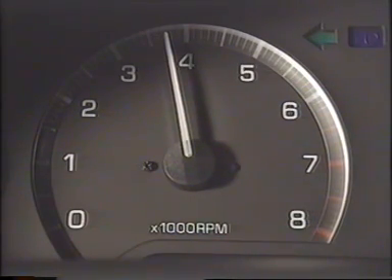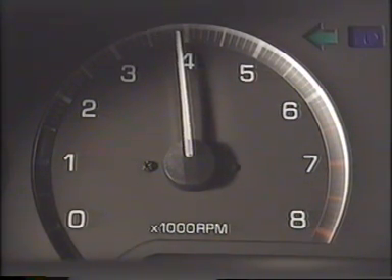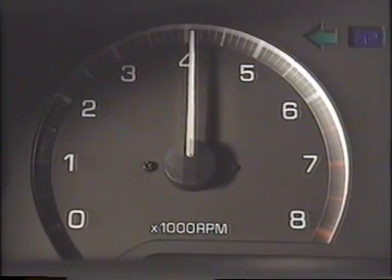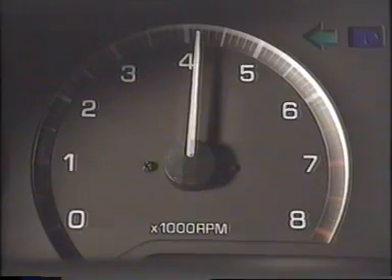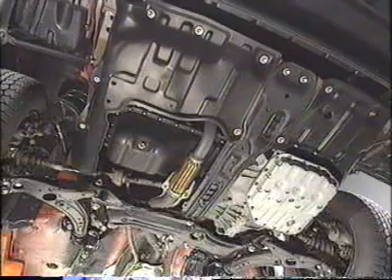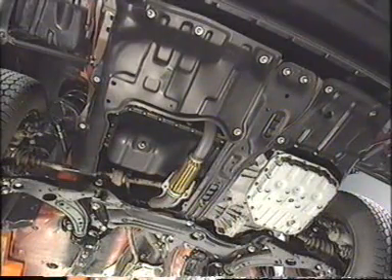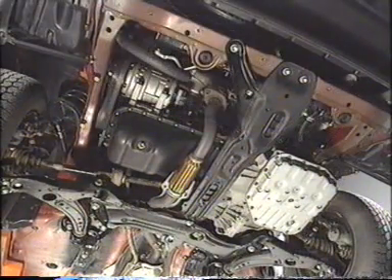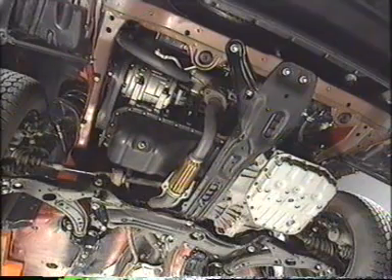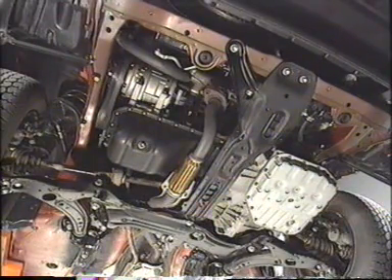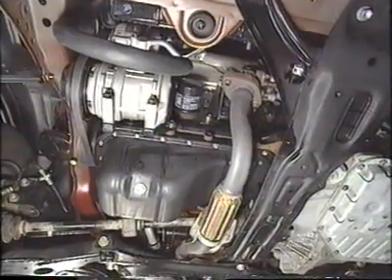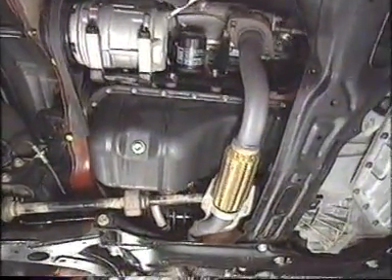We will now study the mechanism by which these vibrating forces lead to vibration and noise. For this purpose, we will study how the engine causes booming. The owner of this car complained that booming is heard when the engine is running at about 4,200 RPM. The engine vibration causes the exhaust pipe to vibrate.